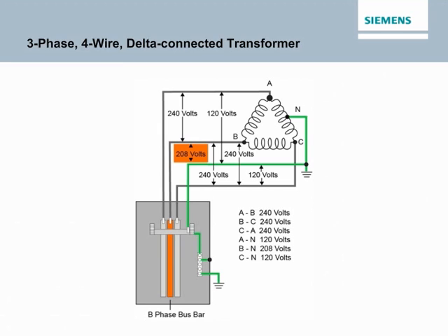It's important to note that not all circuit breakers are suitable for use on the high leg. For example, breakers rated for 240/120 volts can be installed on legs rated for 120 volts, but cannot be installed on the high leg, 208 volts. You may remember that NEC Article 110.15 requires that the high leg bus bar or conductor be permanently marked with an orange finish or by other effective means. This will help to avoid someone connecting a 120 volt single phase load to the 208 volt high leg.